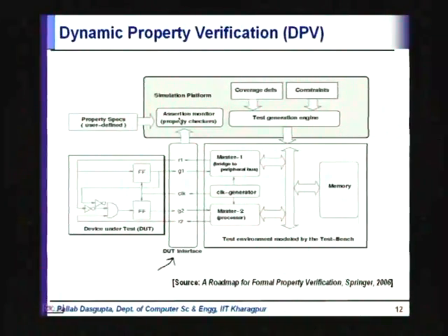Okay. So, we are going to see how we write these assertions, how we can plug them into the design, how the simulator works with these monitors, and then how you can club that with the coverage definitions and make sure that you have adequate coverage of the design with respect to those properties.